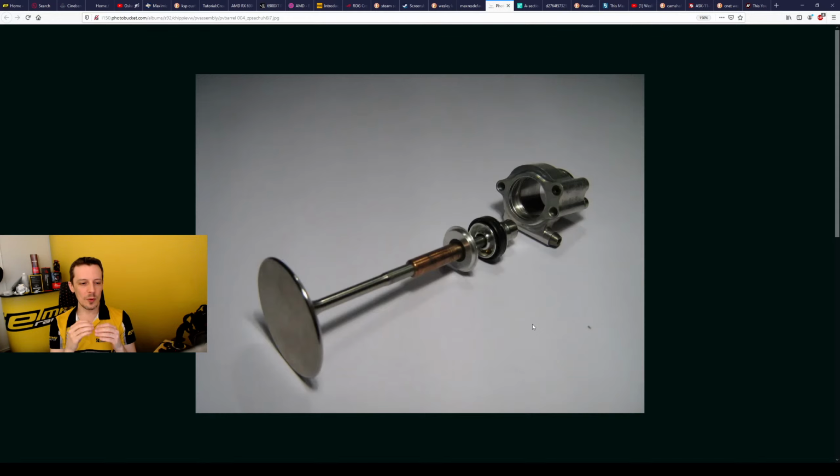So if you have a fuel that has tendencies to produce carbon deposits, then with carbon deposits on the seating area, you can very easily have very high temperature small spots, and when the valve closes, you can start building up issues by having very high temperature areas there. So traditional gas, especially if you're running really rich, will have these types of problems depending on what kind of temperatures you're running surfaces at.